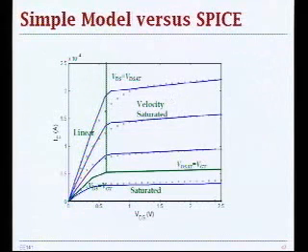What we care about in analyzing MOSFET transistors found in digital gates is this region over here, where you have large VDS, or this linear region, where you have pretty good agreement between SPICE and the model. This region is a transition region. We don't do analog circuits here, so we are never really interested in VDS being equal to 0.8 volts. We want VDS to be either 0 or VDD. And in these corner cases, these models are very good.